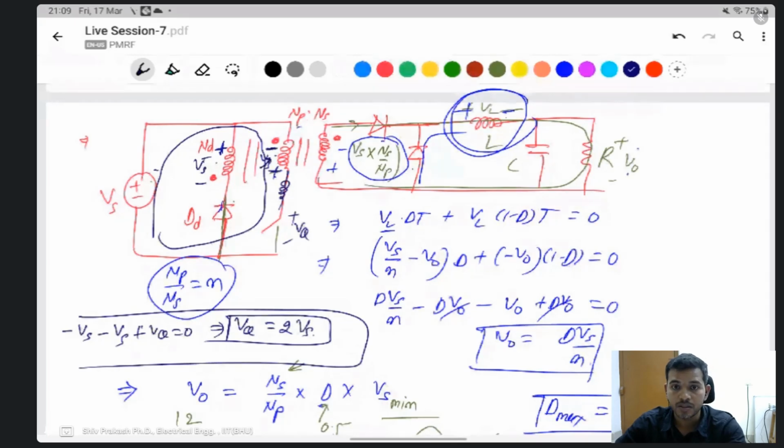Sir, since these two inductors are in series, in the way you have drawn, how does the leakage inductance alone contribute to the spike and this one doesn't? The other one on the red. Yes, sir. We have drawn two inductances in series, and the inductor in black is the leakage inductance, and this is the magnetizing inductance, and the red one with the dot is the reset winding. So how are we saying that the spike is only on the leakage, because almost the same current will flow through both?